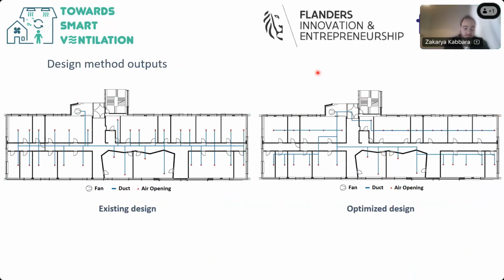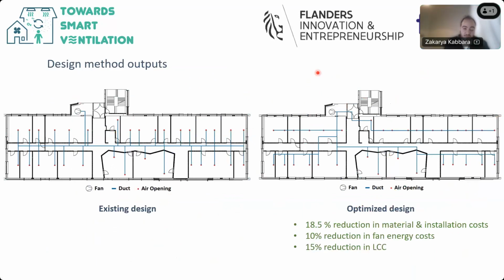And the results that we were able to achieve: an 18.5% reduction in the material and installation cost, and a 10% reduction in the fan energy cost, and that comes to a total of 15% reduction in life cycle cost. But not only this, we were also able to achieve a 25% more balanced design.